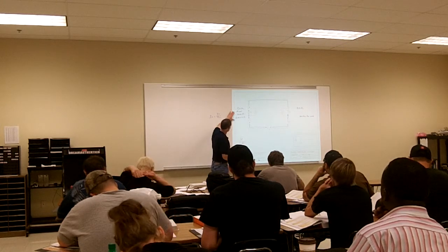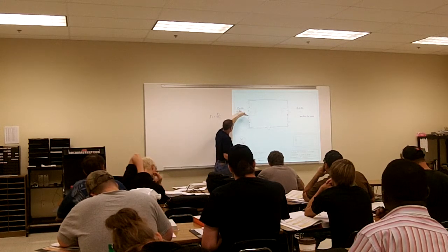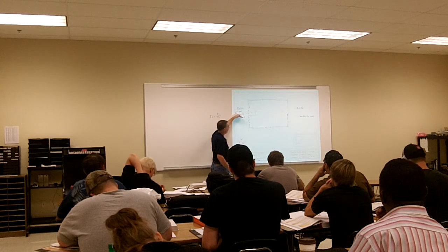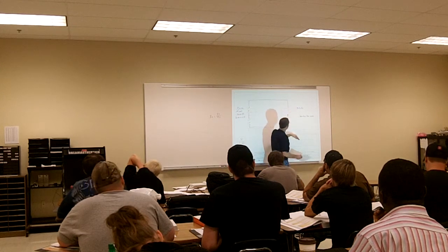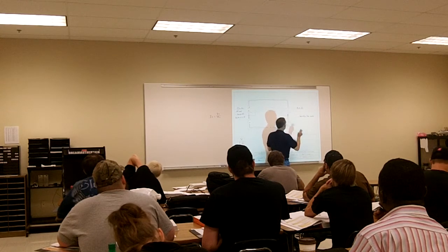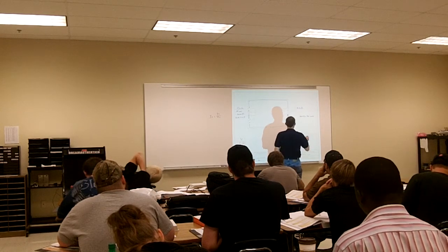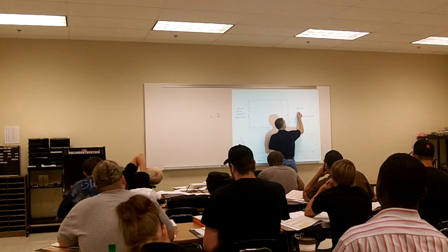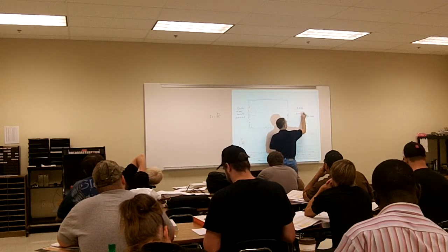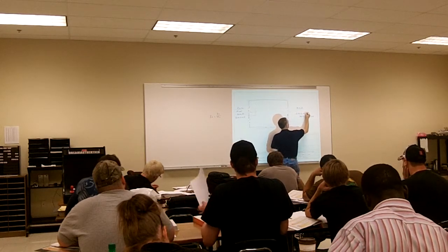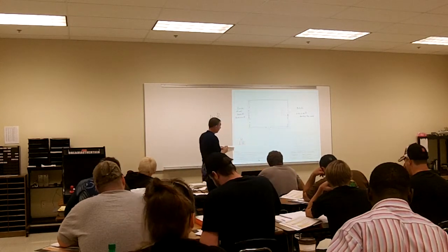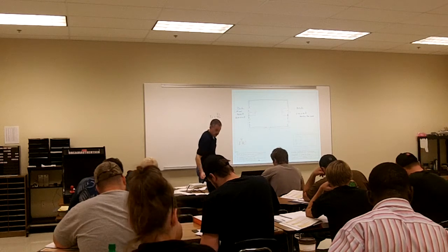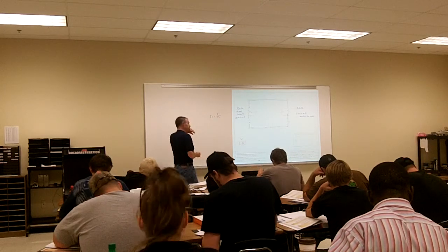So if my total current at my voltage supply is 200 milliamps, that means I'm going to get the same amount of current going through R1. So once we figure out the current going through a voltage supply, then we can also put it going through our resistor. So current always remains constant in a series circuit.